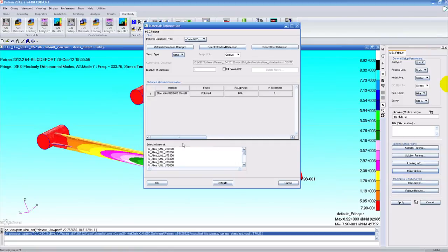So you can see here I have already selected the Welds class, and here I have a number of groups that are readily available, and I already have prepared the stress output group that is going to be the subject of my fatigue analysis. Very useful capability also is that because we're going to have multiple layers, we want to analyze both layers at once. So we're going to analyze it in the top shell and the bottom shell at the same time.